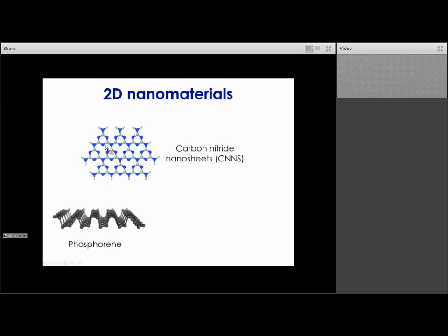Equivalents of graphene, we have phosphorene and silicene. Those materials exhibit a kind of bumpy structure. Phosphorene was first produced in 2014. It is a semiconductor. It can potentially be used as a transistor, and it is known to be relatively unstable in the presence of moisture and oxygen. Silicene here also exhibits that bumpy structure, and it is known to have a band gap that can be more easily tuned compared to graphene.